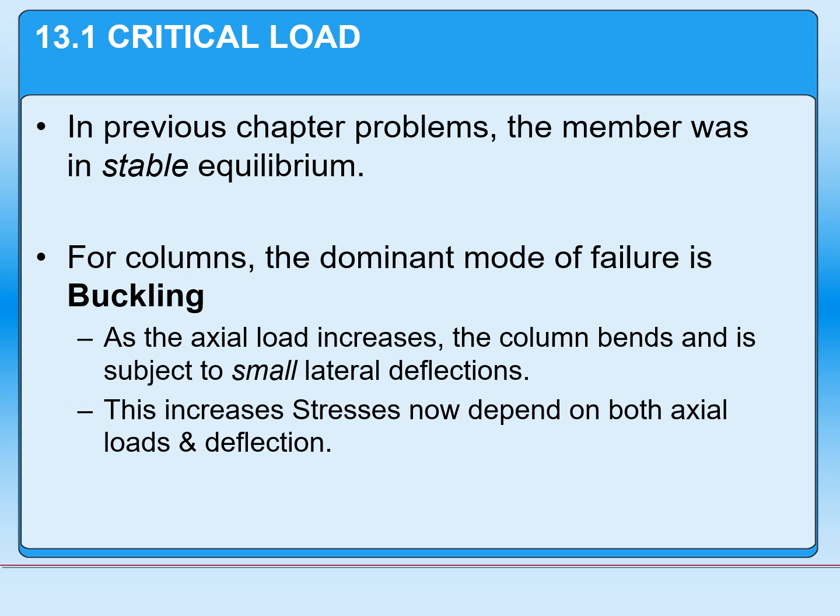When that starts to happen, the stresses are going to increase, not only due to the axial load, but they're also going to be affected by that deflection. As long as that deflection remains small, the column will remain stable. But if it exceeds that level, we'll find that it's no longer going to be in equilibrium.